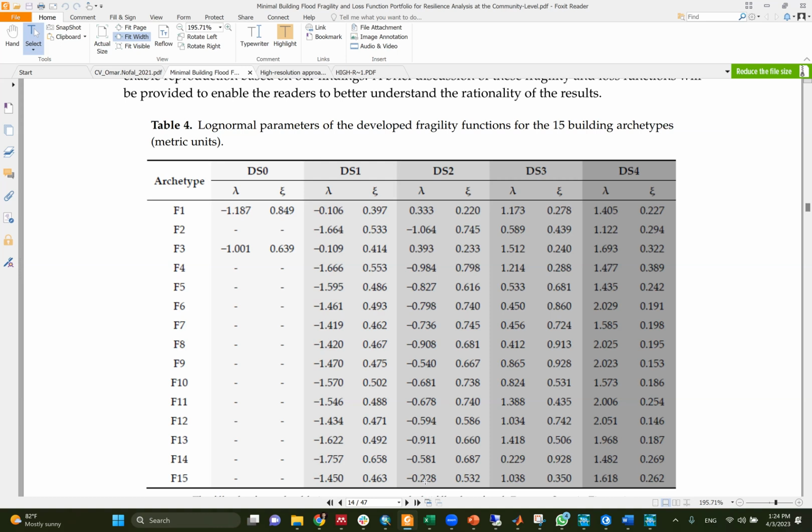So this is for 2D fragilities. How about 3D fragilities? If you guys remember from the last time, we were able to develop a 3D surface for each damage state for each archetype. So how do we read this surface? I will be giving you an Excel sheet that has flood depths and flood duration and a bunch of numbers. If you remember, we had 100 flood depths and 100 flood durations. And then we developed the numbers so that we can develop a surface in 3D for each flood depth and flood duration. We have a point, and then we connect all of them to make a surface, right? So I'm gonna give you this sheet that can develop this surface. So it will be something like this.